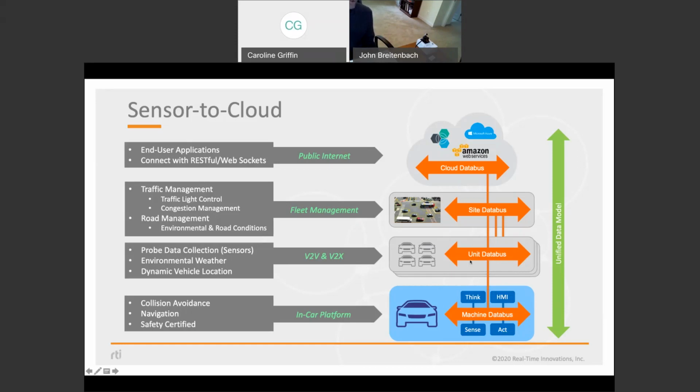Higher levels in an autonomous vehicle world might be vehicle to vehicle or vehicle to infrastructure if we have smart roads. So we might leverage that data-centric nature of the data bus to do some data aggregation and downsampling here within the vehicle, right? Within the vehicle, I do know my position and my speed as well as a whole bunch of other things. But I don't need to push all of that data up to the next level. I might just need a summary. What is my position and speed and my intent for the next 2 seconds, without having to share, for instance, my entire LiDAR point cloud about every single obstacle that I'm seeing?